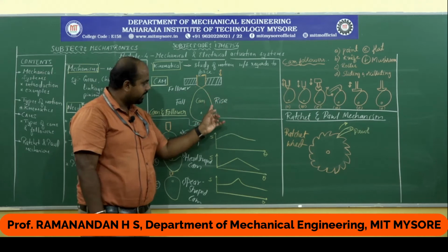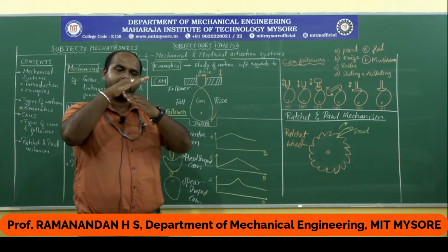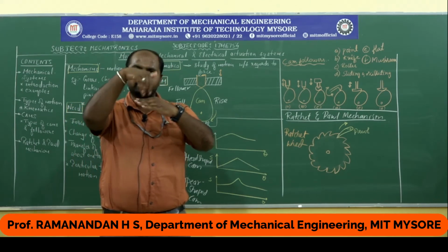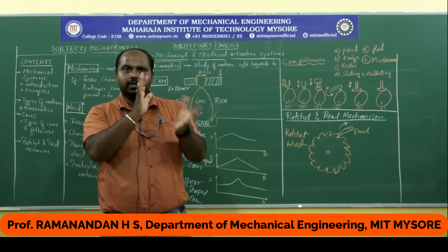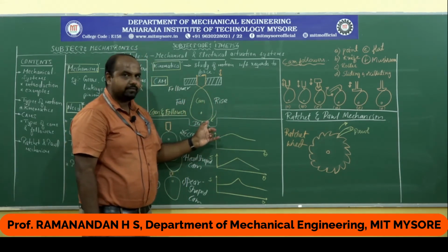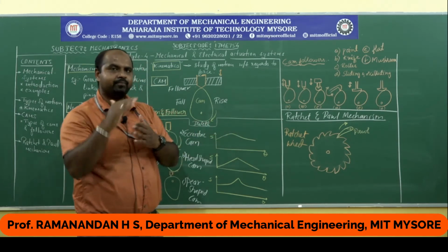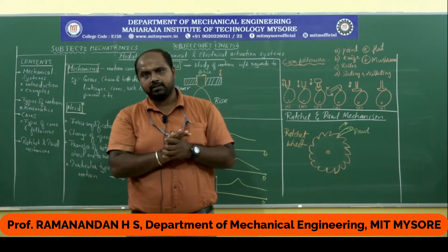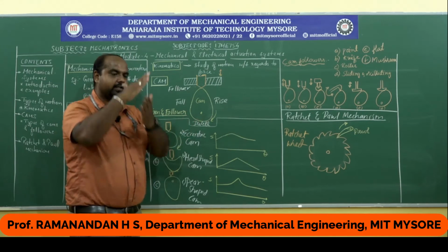So, this rise phase will be defining what amount of time the inlet valve should be open for the petrol air mixture to enter into the combustion chamber. So, there should be correlation with the rise phase profile generation of the cam. They should be predetermined by the application you want. Is that understood? So, dwell phase is usually the inlet valve